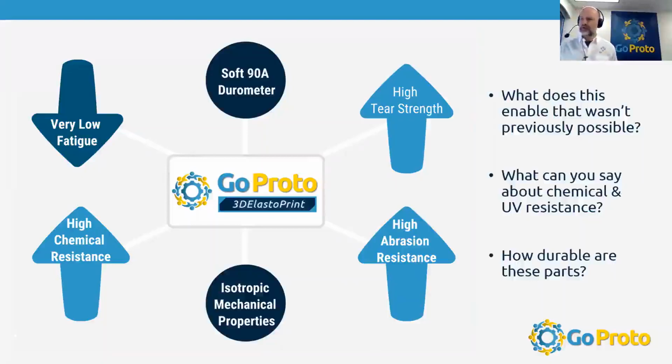It's real important. So there are some material properties that are important on the fulfillment side for us for workflow and so on, but then they end up coming out in cheaper parts or cheaper part price and so on, as well as better part properties like high tear strength, high abrasion resistance. There's also great compressive strength, its ability to take the compression and then snap back. You could compress it and let it sit there for days and days or months and then let go, and it's going to snap back to where it was. That's incredibly important in elastomers.